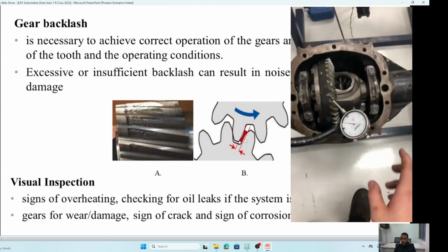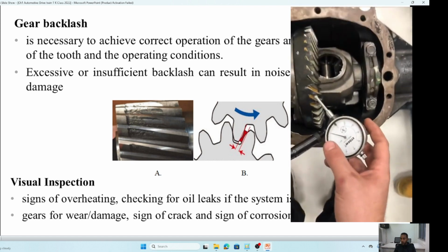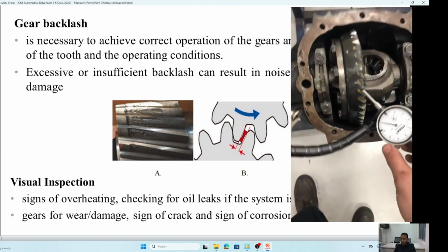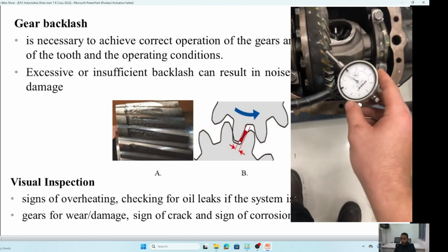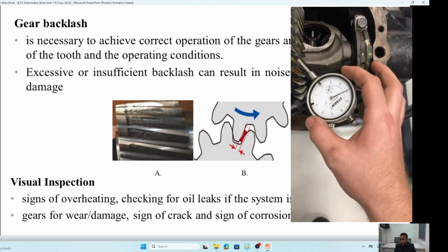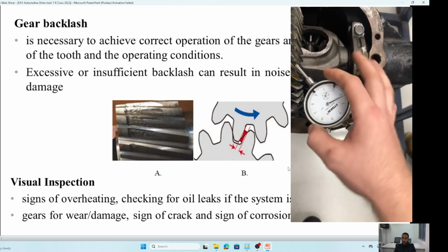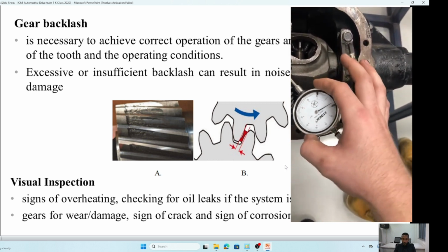To measure this backlash, you must use a dial indicator. To measure it, you need to fix one gear and move the other up and down, or wobble and jiggle it by hand simply. And when it is stopped, you observe the dial and simply record the highest result.